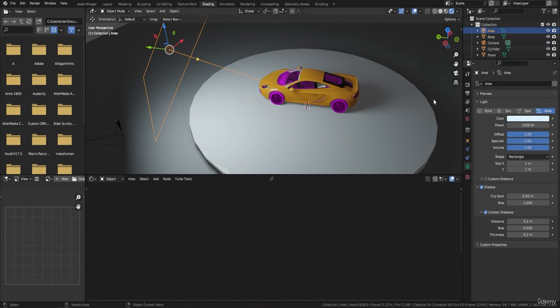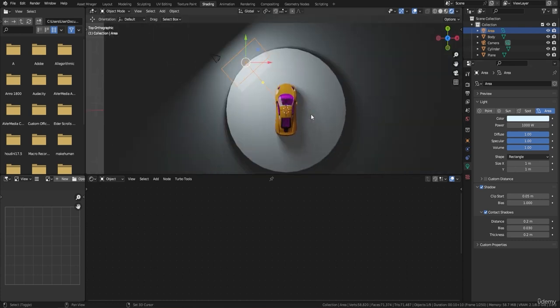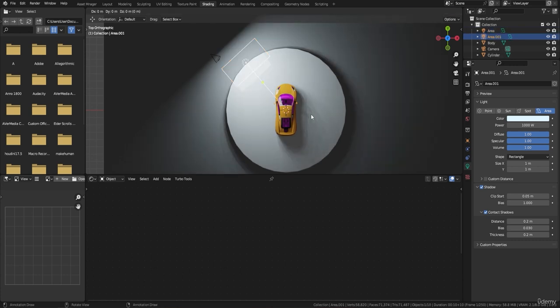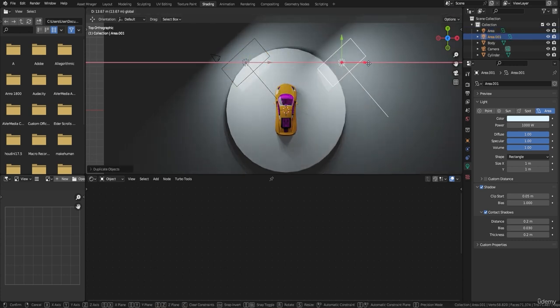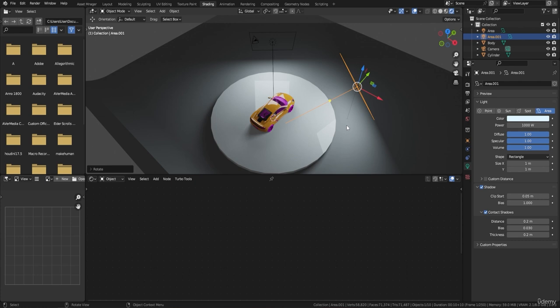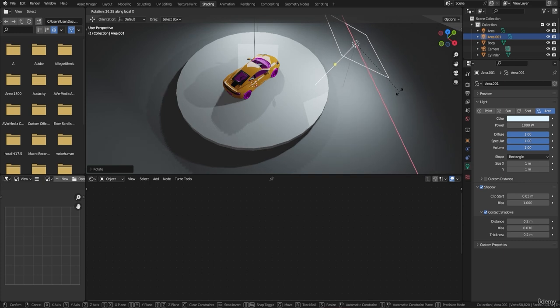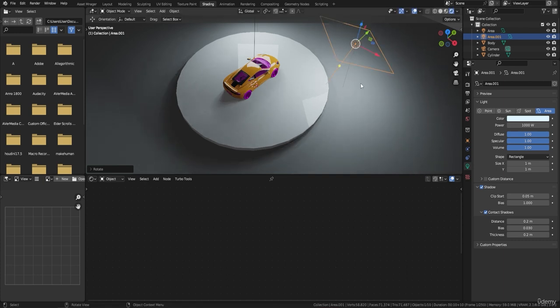And then what I'm going to do now is bring in another light. So I'm going to basically grab the same light. So this one here, I'm going to go over the top like so. I'm going to press Shift D. Like so. I'm going to then bring this one over and spin it round. So R, Z, let's spin it round. And then I'm thinking now I want to actually bend it down so that it's touching the floor round about here. So if we then press, let's have a look, R, X, X, bring it down. We want it touching the floor round about there.